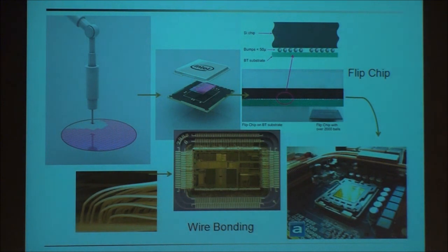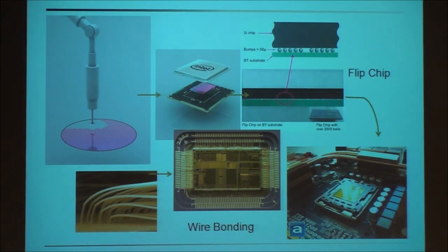So the importance of that is, for example, in the IC chips and all that, we pretty much know that nowadays, since there are so many inputs and outputs, to the point that, flip chip provides high density interconnects for you to package those chips onto a substrate, onto a package, and then in the end you assemble it into your computer devices. Or in a traditional way, people do wire bonding so that you can bond your chips to a package so that you can handle this in a much easier way and assemble it onto a circuit board.